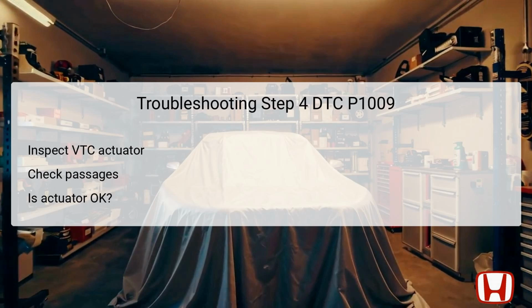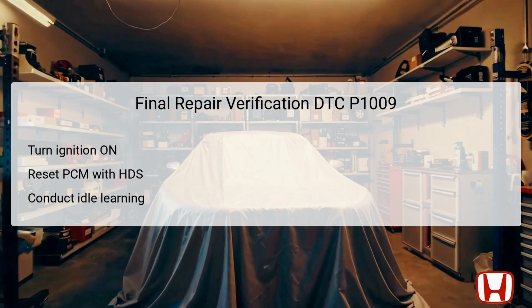If the actuator is confirmed as not functioning properly, it should be replaced. Conversely, if the actuator checks out, any clogged passages should be cleaned to prevent future operational issues, followed by a repair verification. For final repair verification of DTC P1009, start by turning the ignition switch to the on position.